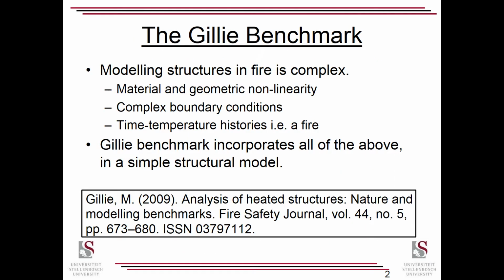So why are we doing this? Well, modeling structures and fires can become quite complex due to a number of reasons. For instance, material and geometric nonlinearity, complex boundary conditions, and time temperature histories, which is essentially a fire. So the Gillie benchmark is quite nice because it incorporates all of the above modeling difficulties, but the actual structural model is quite simple, so it's easy to check.